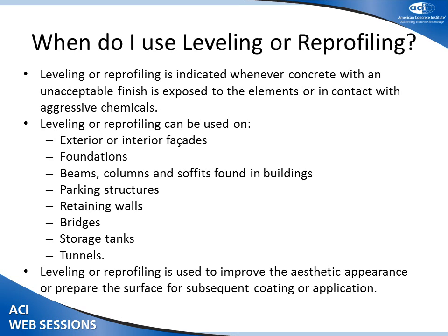Leveling materials are going to be used whenever I have an unacceptable finish, either exposed to the elements or to a chemical, aggressive environment. Leveling materials will be used on exterior or interior facades, foundations, beams, columns, and soffits, parking structures, retaining walls, jersey barriers, bridges, storage tanks, tunnels. Once we have the surface either leveled or reprofiled, it allows us to properly install, or gives a sound foundation for, an aesthetic or protective coating.